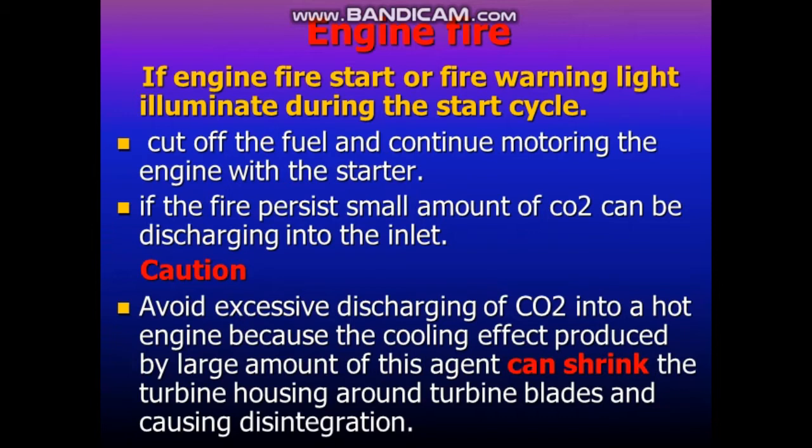If an engine fire starts or the fire warning light illuminates during the start cycle, what should you do? You have to cut off the fuel and continue motoring the engine with the starter.